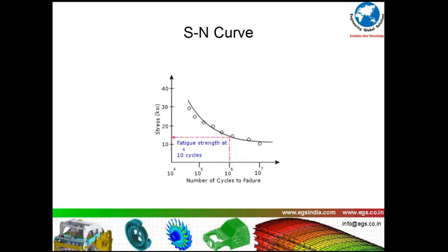Is that going to influence your fatigue life from the actual stress? No, it is going to be only the mean stress and versus that the stress amplitude. That is why I'm putting together this particular slide to enforce upon the audience that it is designed for life based on operating stresses, not based on one-of-a-kind stresses.